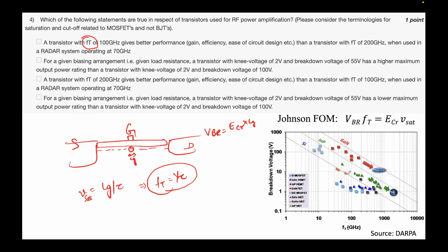It's not that they are only for silicon, but sorry, not HBTs, LDMOS, and there are a few other devices for silicon. For indium phosphide we have the HBTs, and for gallium nitride we have the HEMTs, the various flavors of HEMTs that are there. Silicon, obviously MOSFET is always there. I'm not saying MOSFET is not there, but yeah, so these silicon germanium HBTs are there. There are some gallium arsenide HBTs, and this is just the table you have.